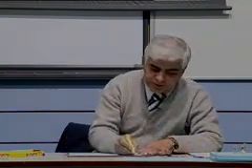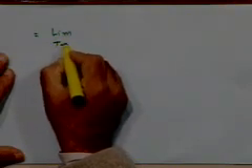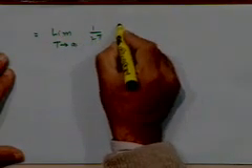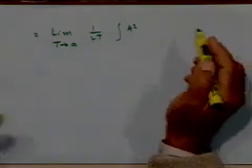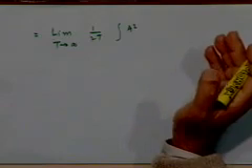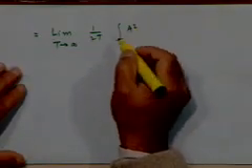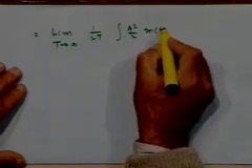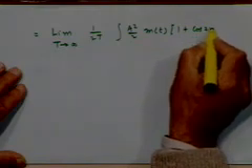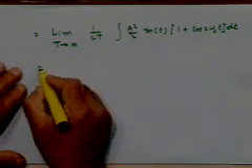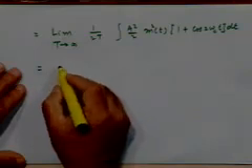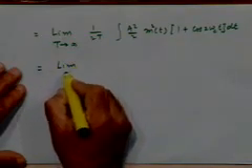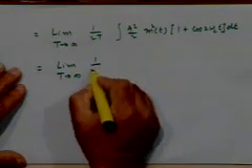So if you were to do that, this would be equal to, in our case, the limit as T tends to infinity of 1 by 2T times the integral of, let's use the trigonometric identity to write cosine square omega ct in terms of the sum and difference components. What is cosine square? It will be m square t into half of 1 plus cos 2 omega ct, dt, which is from minus T to plus T, consisting of two parts.